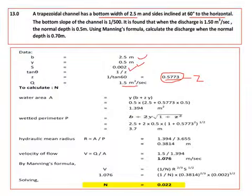Here discharge is given for the first set of calculation when the normal depth is 0.5 meters. You should calculate the new value of discharge when it is 0.7. So you have to use Manning's formula. Therefore n has to be calculated. In the first set of calculation n is not given, so we are calculating n.